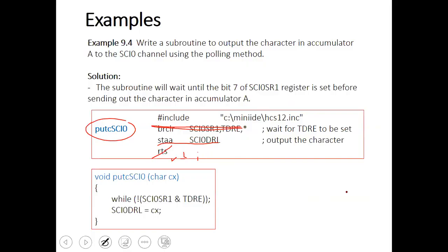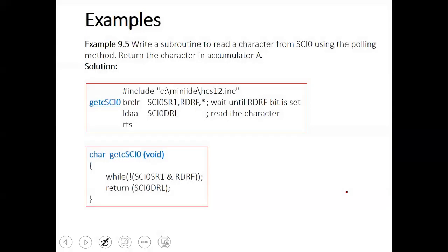Okay, so it's kind of confusing. Some maskable interrupts, such as the IRQ, don't have flags, so you don't need to clear flags. For the RTI and the interrupts related to the phase locked loop and the A to D, to clear the flags, basically you need to write 1 to the flag. And it is becoming more confusing. When you look at the A to D, we said there are many ways to clear the flags, if you remember. Different approaches to clear the flags. We have the fast clear option also available.